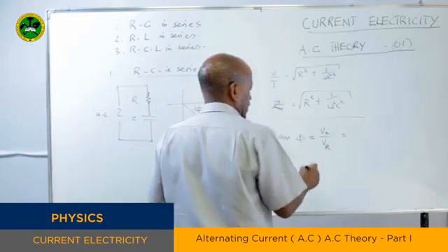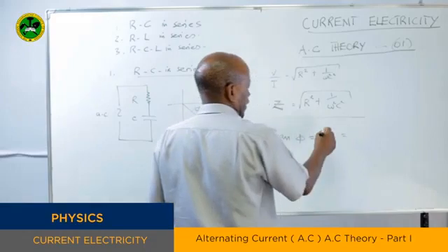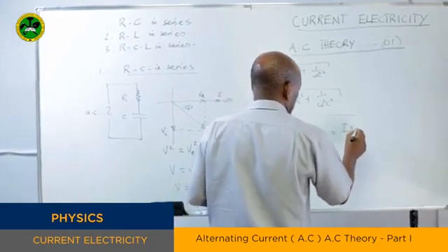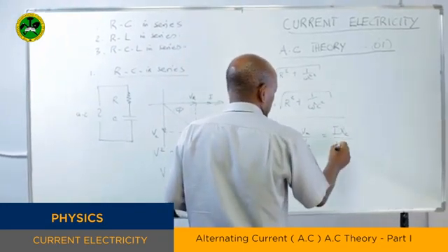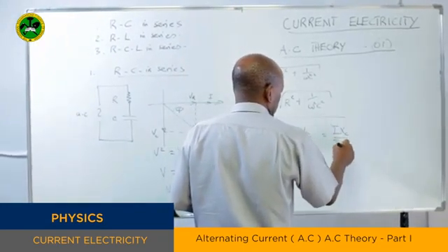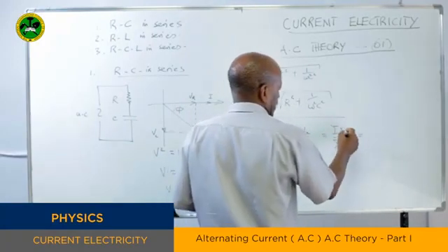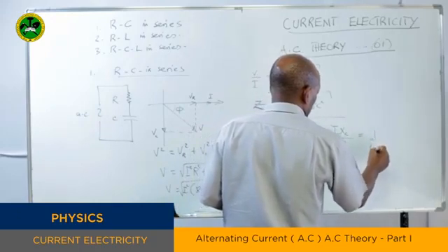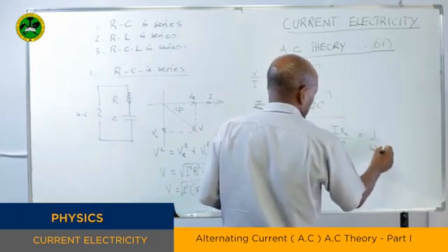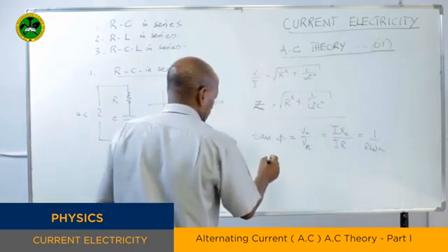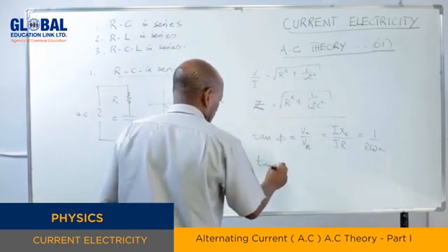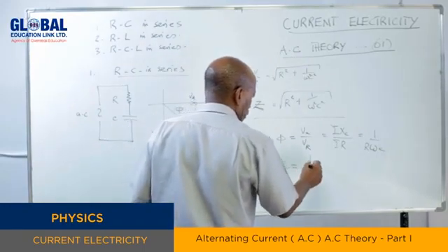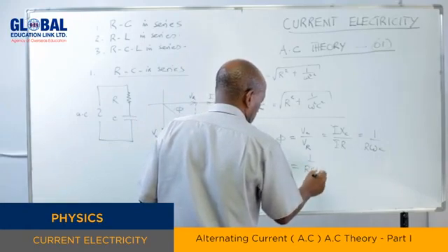And as we have already said, the voltage through a capacitor is equal to I times the capacitive reactance, and the voltage through a resistor is just equal to IR. So the current will cancel, and the capacitive reactance will just be equal to 1 over omega C. We divide by R, and you will find that tan phi here is equal to 1 over RC times omega.